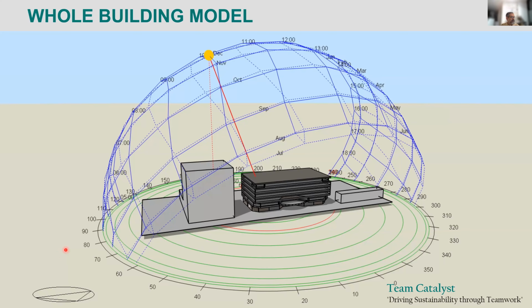And if you look at this sun path diagram, you can see very clearly that in summer, which is December, January, February for us, by the time it's 10 a.m., the east facade gets full sun. There's no real shading from the surrounding buildings. This is the north facade for us in the Southern Hemisphere. That's the sun-facing facade.